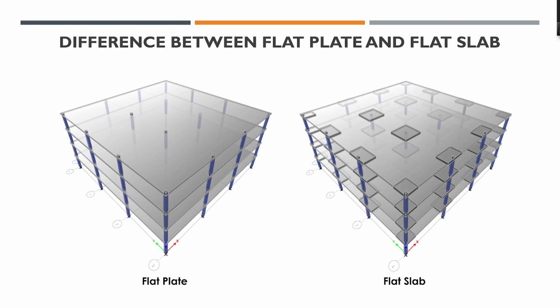Because normally in a tall building, they want to achieve one floor per week speed, which means it has to be extremely fast. You have to put up all the formwork, cast the concrete, and remove it within one week. Some projects do 5 days, 4 days per floor. Very, very fast construction. So if you do that, then everything has to be flat. You don't want any problem. You just take out the forms, move to the next floor, and do it very fast.